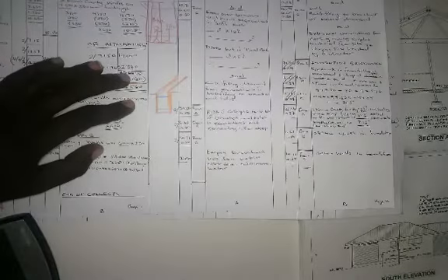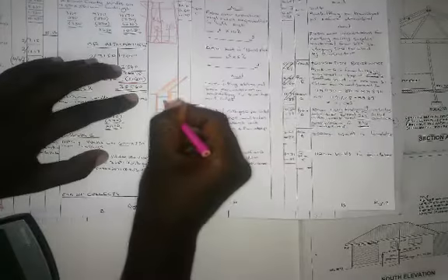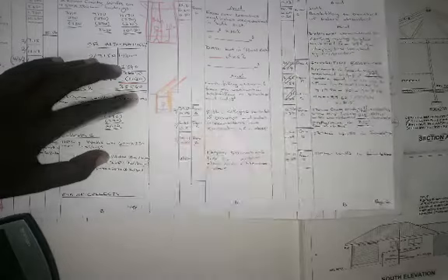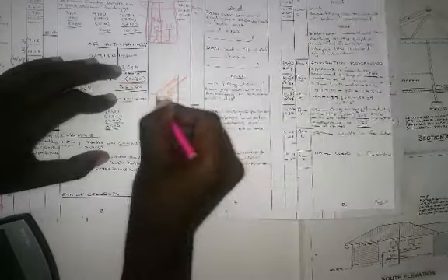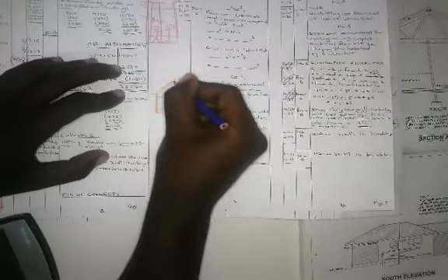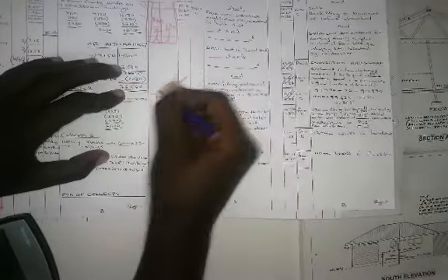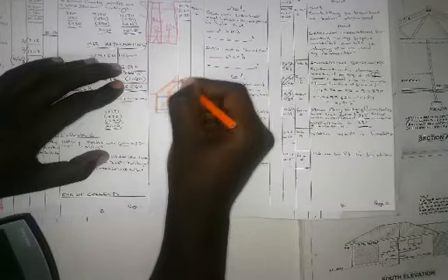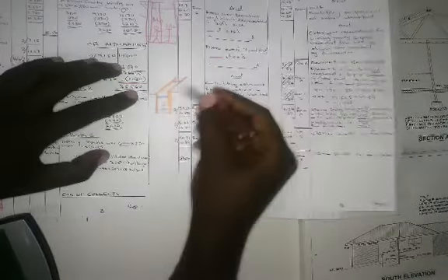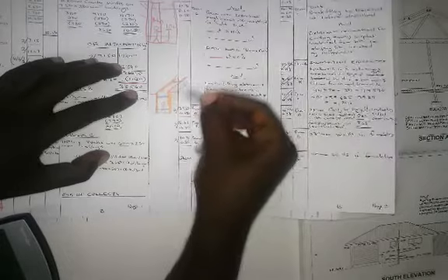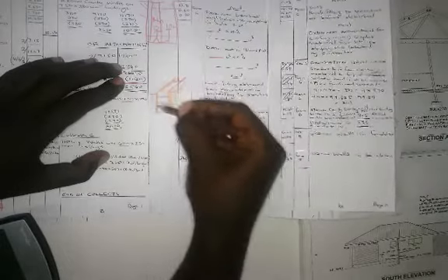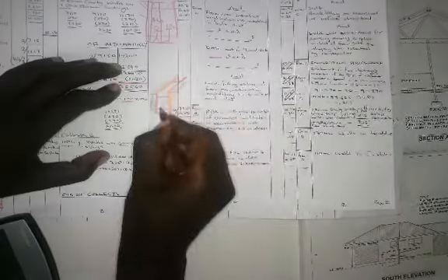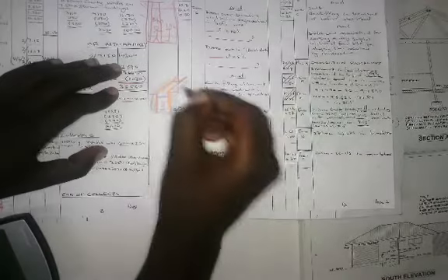So this thing goes all the way across your trench. Okay, this thing goes all the way along, because what we don't want is for your person who's working here to have the soil collapse into him. So we need to make sure we put in even a steel shoring cage into this, so that this person here is protected against the collapse of the soil.